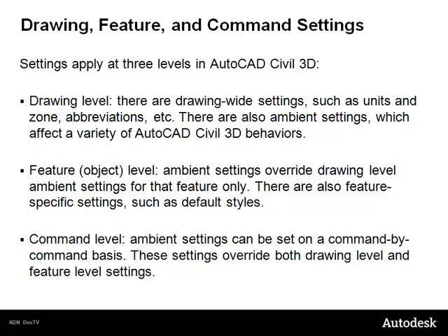At command level, ambient settings can be set on a command-by-command basis. These settings override both drawing level and feature level settings. For more information on settings in general, you could refer to the topic Understanding Settings in the AutoCAD Civil 3D User Guide.